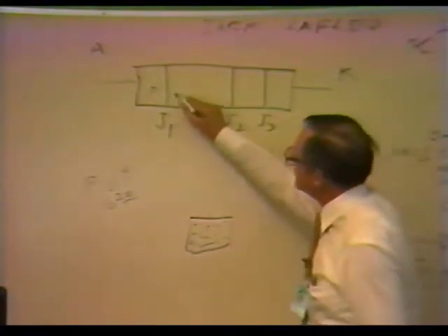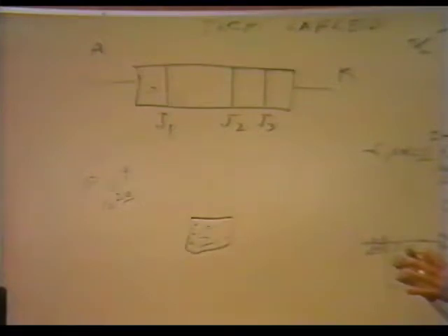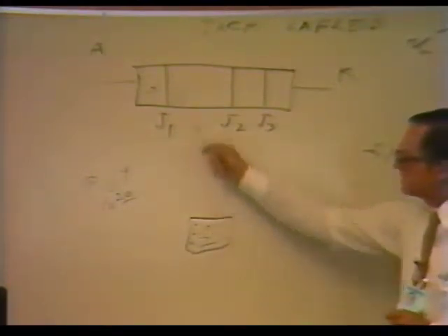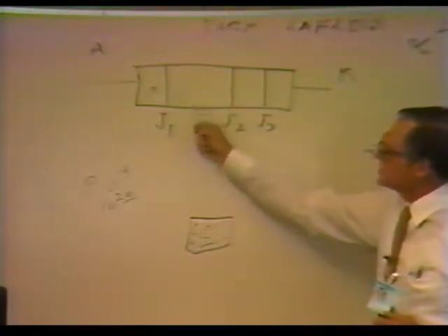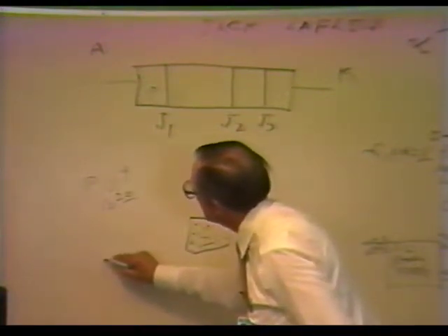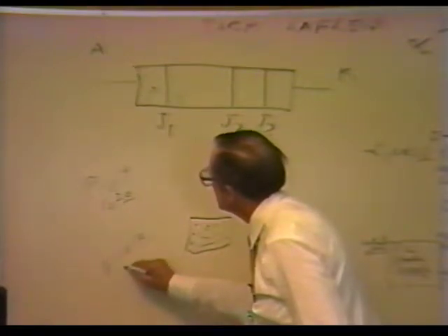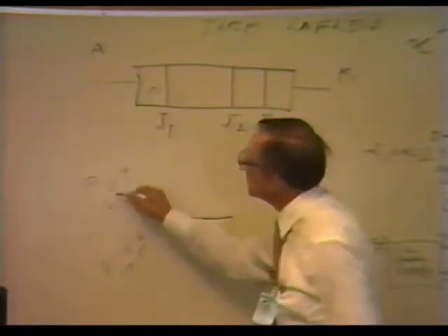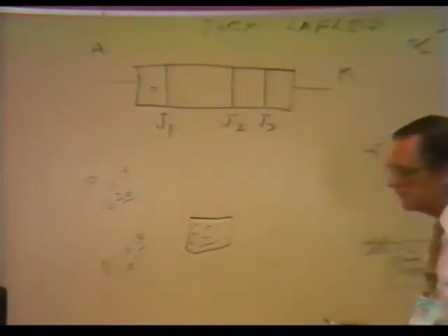Now, when we come to the N region, I think they use phosphorus, and they dope these with carriers and phosphorus atoms, and it is a similar doping as we did to the P region. And in this junction area, you notice I always draw it larger than the others. We put the doping levels fairly low. It would be N, and it would be a donor, and it would be like 10 to the 14th, 10 to the 15th. Much lower than the other. So the doping level here is fairly low.